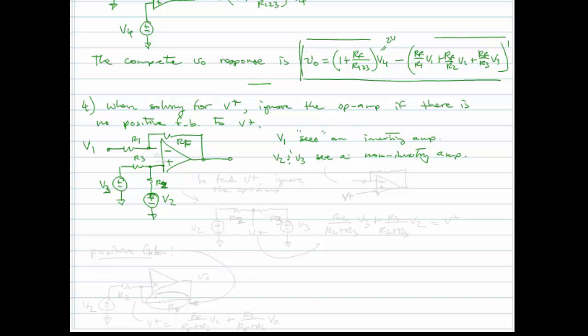And so what you need to find out along the way here is if it's a non-inverting amplifier, then you're applying some external voltage to the non-inverting input right here. Right? So you need to know what this voltage is at the positive terminal, call it V+.